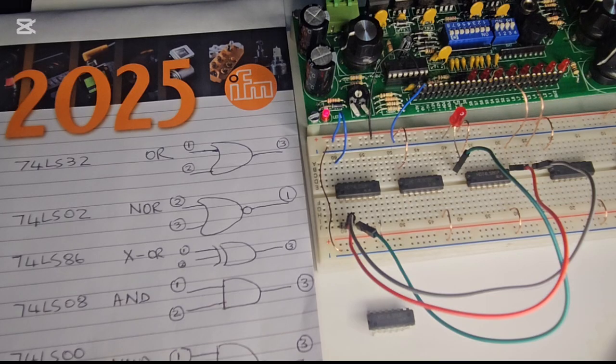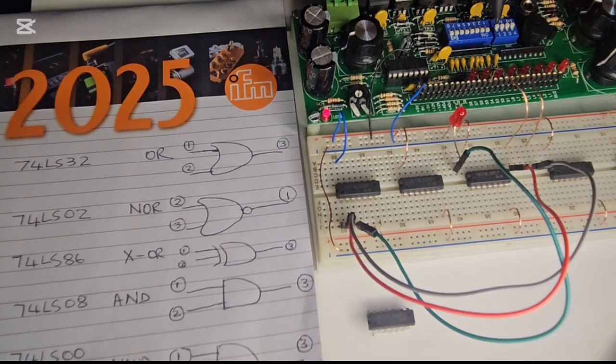So it can be anything, meaning in the real world, it can be a pump, it can be a valve, it can be a lamp, it can be a buzzer, it can be a lot of things that you can be controlling. But then I want to see if the OR logic works. So we said in the OR gate, if one of the inputs is true, the output should be true. So let's test that. So I connected input 1 and input 5, if you look at this one.